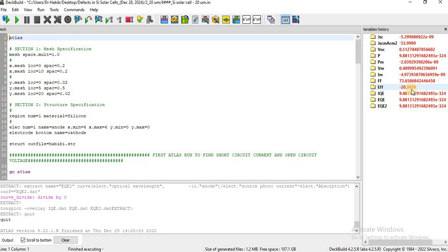There is going to be radiation induced or metal impurity defects, which is going to worsen the recombination as well. So there is going to be efficiency loss in materials with high defect densities or after defect inducing processes like ion implantation, oxidation, diffusion, etc.